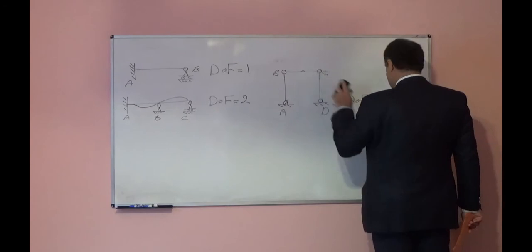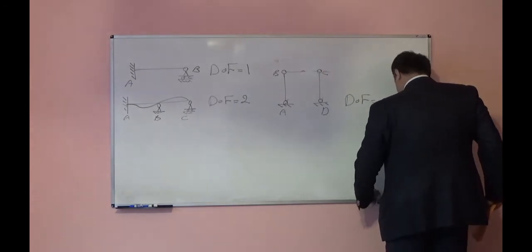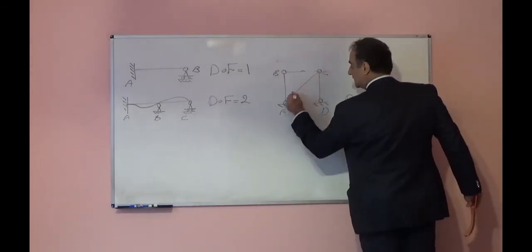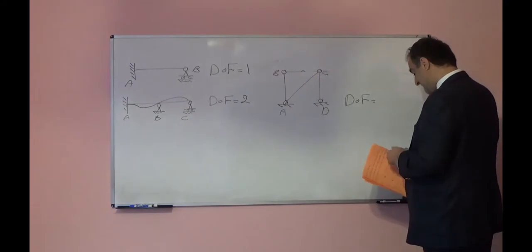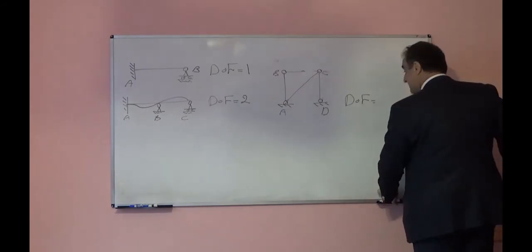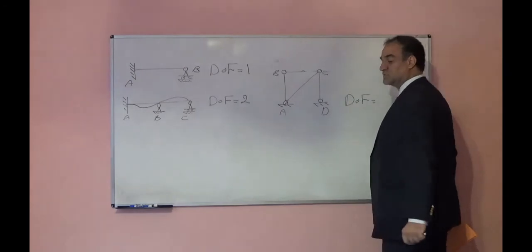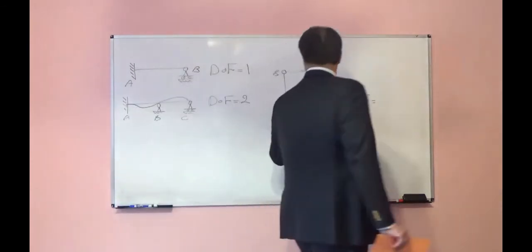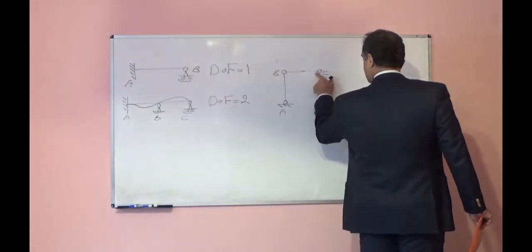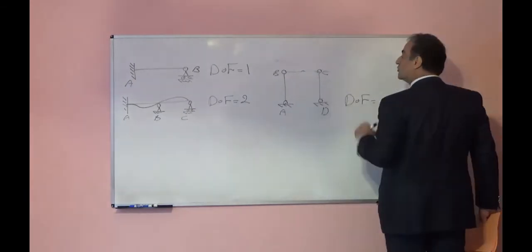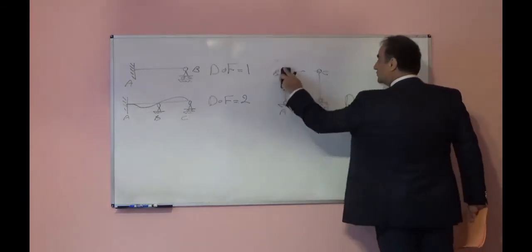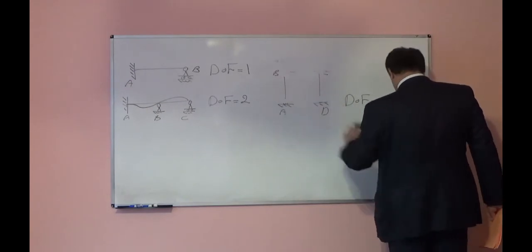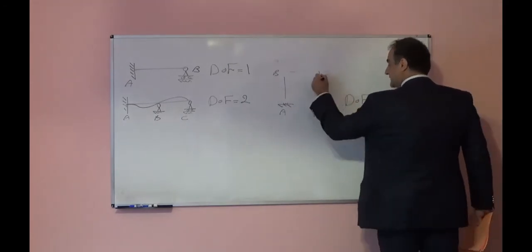if you add one member like this, one diagonal member, now this is stable because we have a truss structure. It cannot move in the horizontal direction. So we add only one member in order to make it stable. So one lateral deformation we can have in this frame and two node rotations we can have here. So degree of freedom totally will be 3 for this frame.